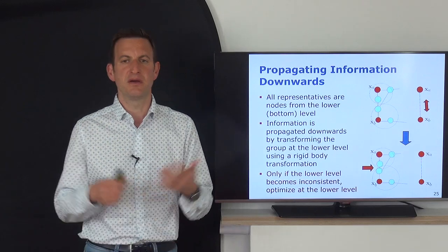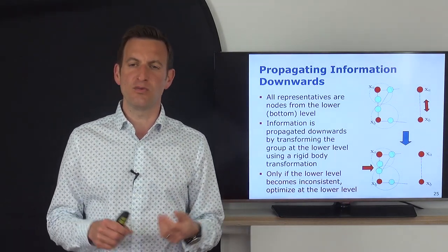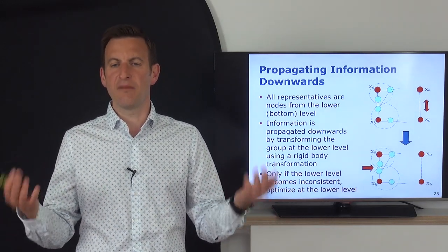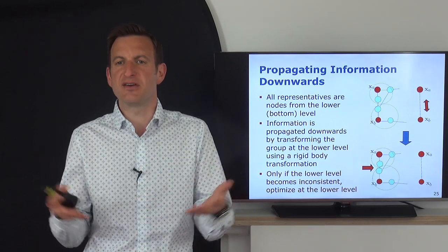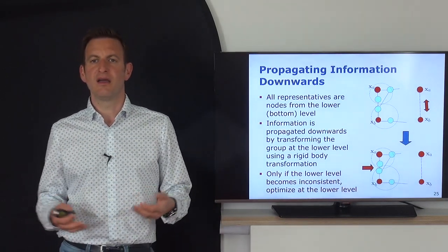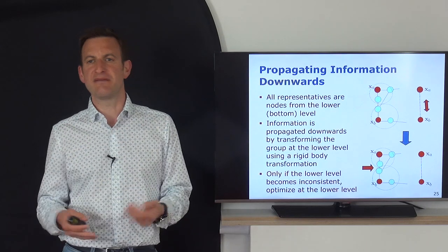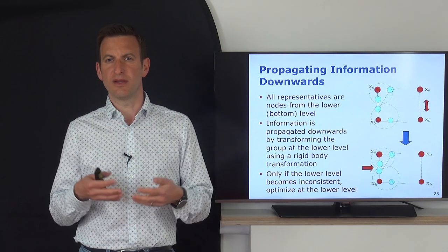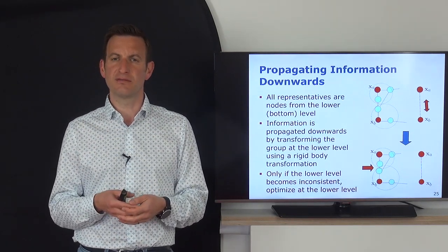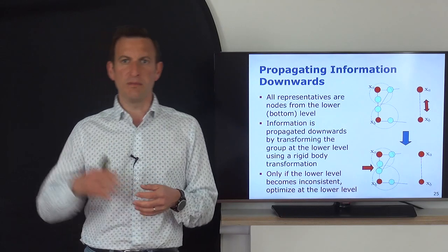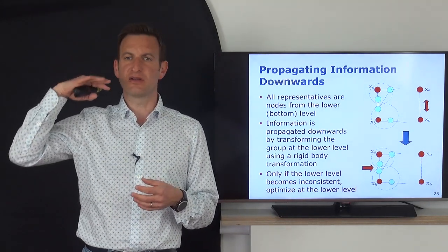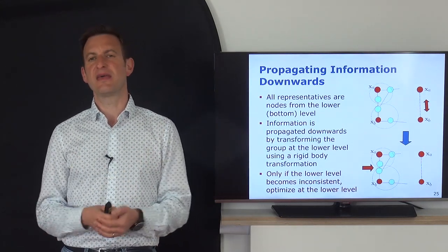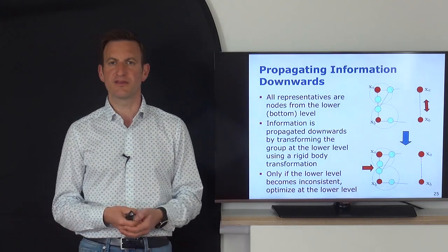And we may have some constraint to that. Whenever a node moves less than 3 centimeters, I don't really mind about that anymore. Because, obviously application specific, but let's say 3 centimeters shouldn't affect my local map so far. And then I say I'm fine not having the perfect map. Okay? And then we are done already. So we introduced this idea of a hierarchical pose graph. We explained how we build the pose graph, we know how to optimize a certain level, standard pose graph SLAM, and then we explained how to propagate the information downwards. And that's actually all we need to know in order to build such a system.